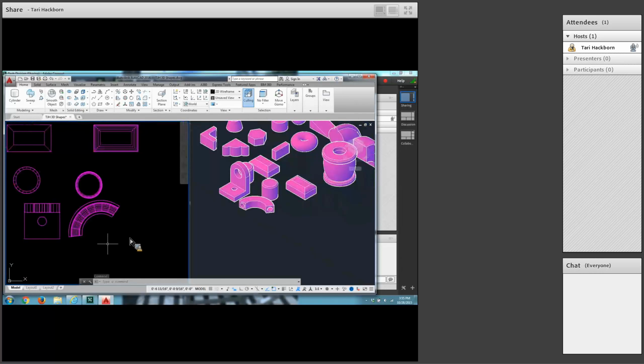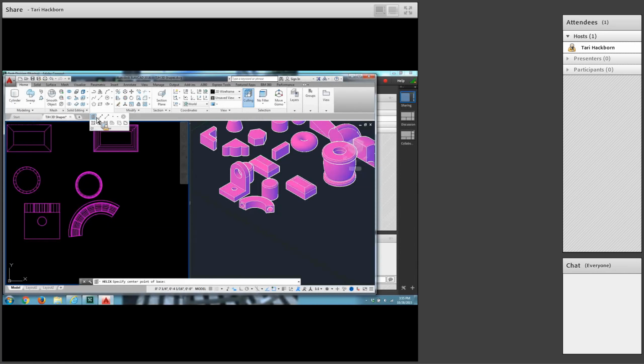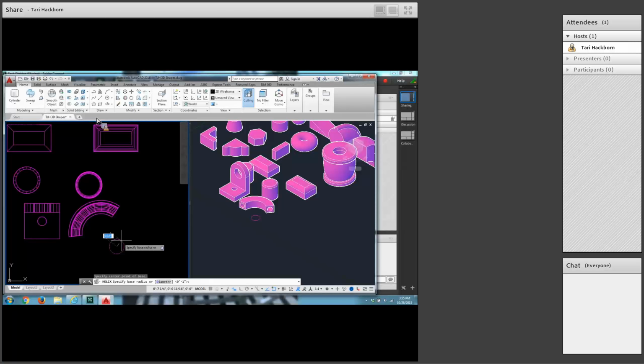Where do they want that helix to be? Kind of out here in this area. Let's find the helix. There's a helix tool now in AutoCAD. The helix command is in those extra draw tools. So click the starting point in the approximate location. You can go back and look at page 47 again. This is approximate. Let's type a ½ inch for the radius.